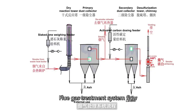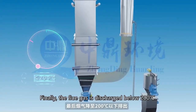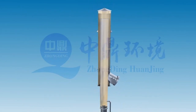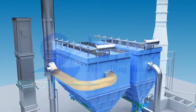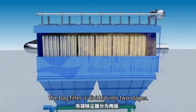Flue gas treatment system process. Finally, the flue gas at temperatures below 200 degrees Celsius is directed into the dry reaction tower, where lime powder is used to neutralize the acidic substances in it. The flue gas, laden with dust and having undergone desulfurization, is discharged from the dry reaction tower and enters the bag filter. The bag filter is divided into two stages.